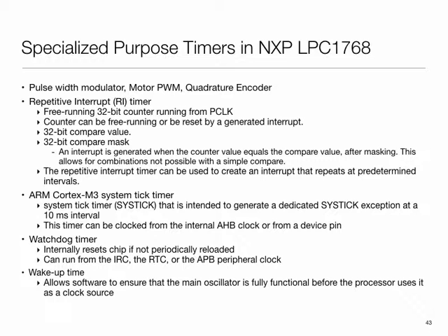Some platforms like BeagleBone, which I had mentioned, actually have special units, special processors. BeagleBone, which is a TI chip, has something called PRUs, which are specifically meant for such real-time interaction. So a big part of what distinguishes an embedded processor from, let's say, an Intel general purpose processor chip is this rich set of functions.